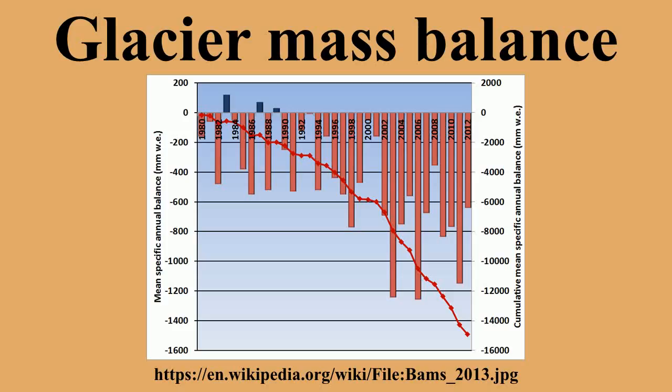Laser altimetry provides a measurement of the elevation of a glacier along a specific path, e.g., the glacier centerline. The difference of two such measurements is the change in thickness, which provides mass balance over the time interval between the measurements. Again, a good method over a span of time, but not for annual change detection. The value of geodetic programs is providing an independent check of traditional mass balance work by comparing the cumulative changes over 10 or more years.